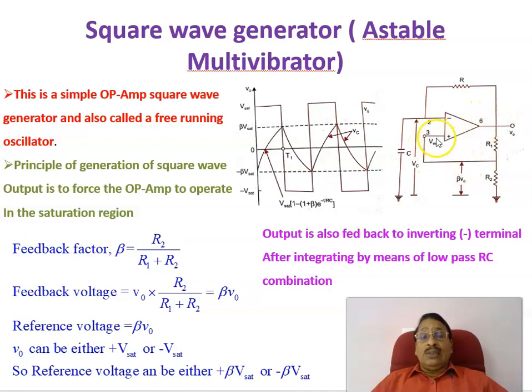This is the reference voltage coming to the non-inverting terminal, and to the inverting terminal, the output is fed back through a resistor, with the capacitor grounded, forming an integrating path.